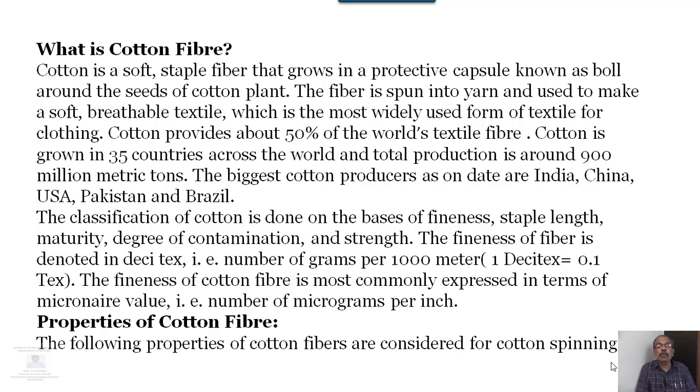So the classification of the cotton is done on the basis of fineness, staple length, maturity, degree of contamination, that is trash, the extraneous matter which the particular fiber acquires when it is exposed in the environment, when the fiber is growing there, and the strength.